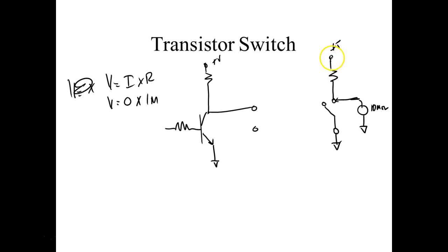Well, if it drops 0 volts, that means the 5 volts is not dropped. That means if I have plus 5 volts there, I'm going to have plus 5 volts there, and my meter's going to measure 5 volts, because my switch is open. I'm measuring across an open in a series circuit. Any open in a series circuit, the voltage appears across it.